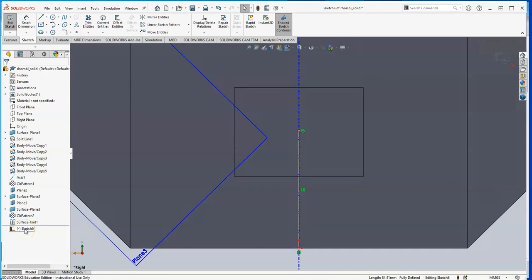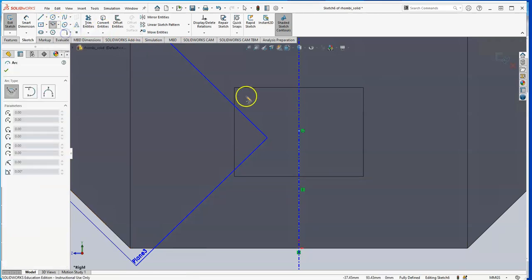Rather than create a circle out of that, what I do is create a semicircle and then join the edges of that with a straight line, so you get a sort of wedge shape, like a wedge out of an orange. Then I'm going to revolve that around its center to cut out a hollow out of the middle of the solid. So I'm still on sketch 6 here. If I click on center point arc and select the end of this line as my center.